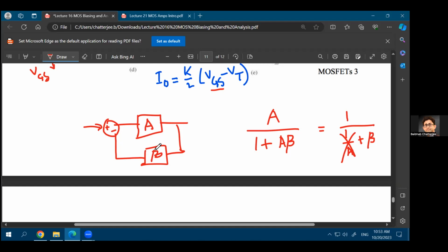You have already seen examples where you found out beta in your homework number 3 or homework number 2, even your exam number 1, you had to find out beta, the feedback factor, right? And remember that the feedback factor was a function of resistances. And resistances, the ratio of resistances, if the resistances are created using the same batch, if they are fabricated in the same batch, usually the ratio of the resistances remain a constant or very close to a constant, even though the absolute value of the resistance can change.